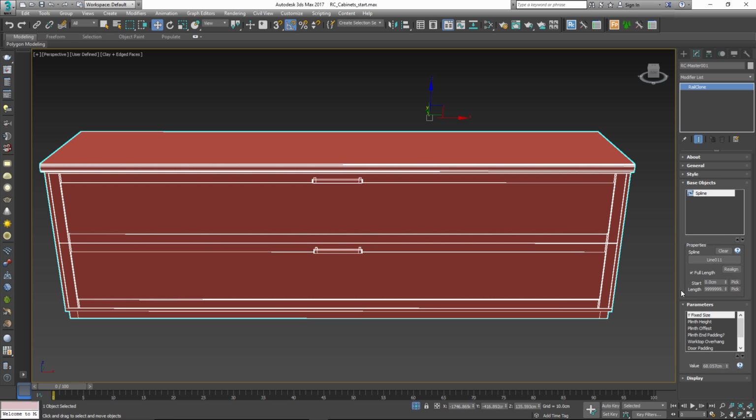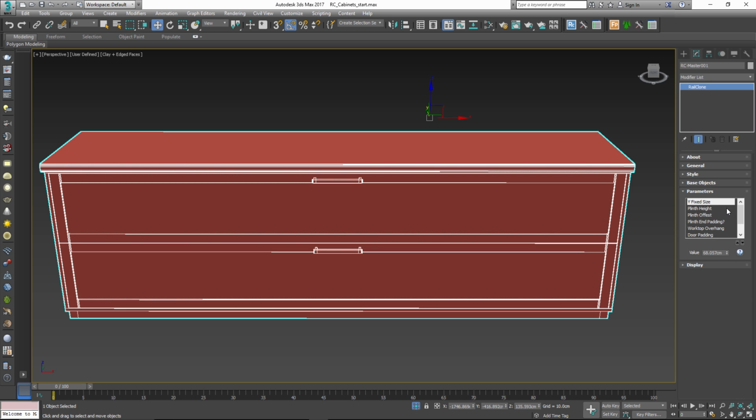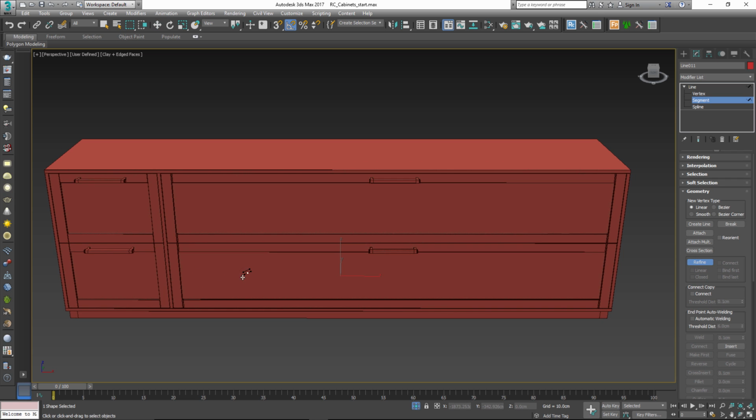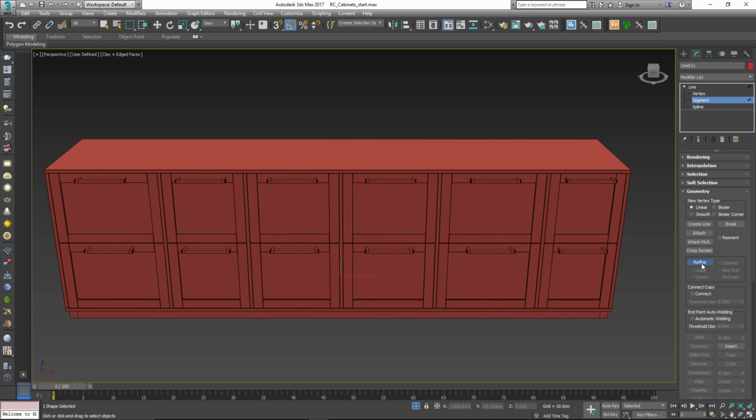The height of the worktop and the cabinets is derived automatically from the doors, so if you change the door segments, the rest of the style updates automatically. Doors themselves are created by adding vertices. One single door is scaled automatically between two vertices. Doors are sliced so that only the midsection scales, minimising the chance of incorrect deformation on the sides.